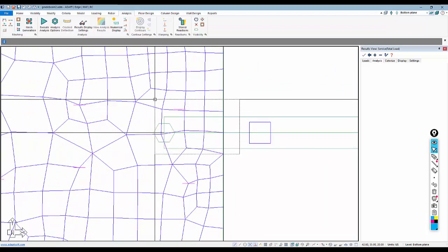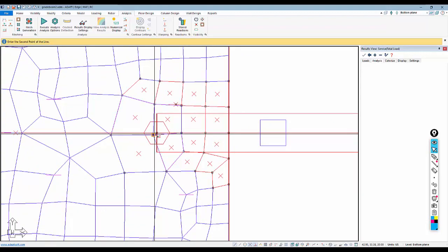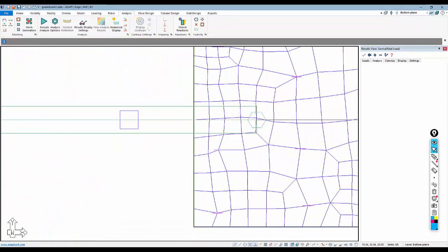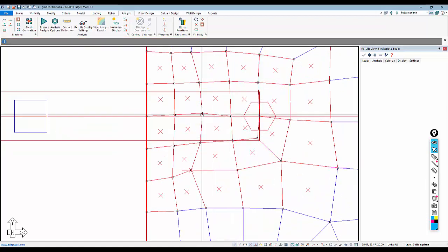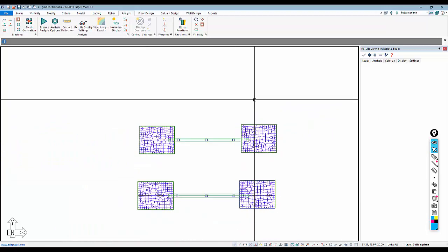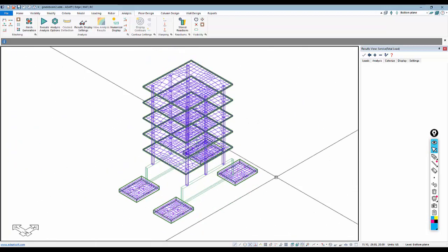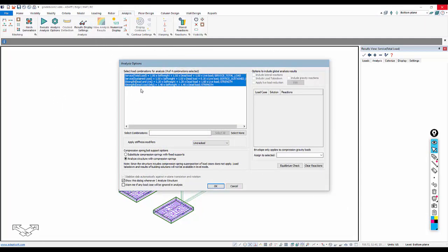And over here, goes over to the beam center line. Same thing on this last beam. So we're moving to center line and also to endpoint of beam on that last set of nodes. Once I've done that manual modification, I'll go back to the main model globally and we're going to execute the analysis. We don't need to redo the meshing, we just did that and then we made the manual modifications.